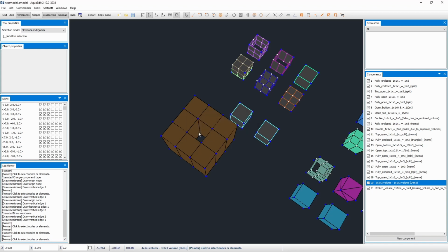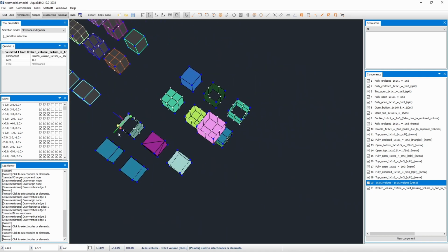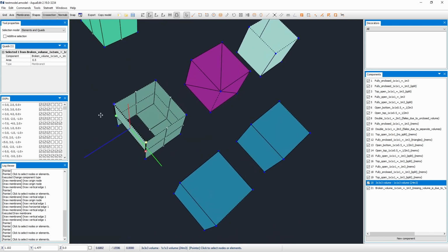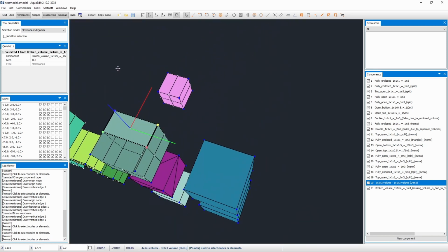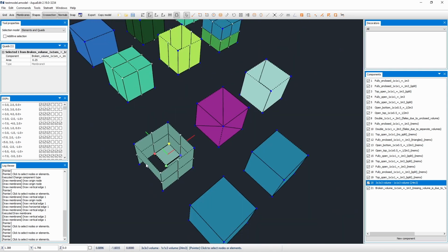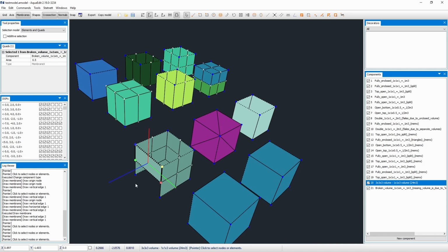Since we are looking at volume calculations, let us also see how the new algorithm deals with holes in the geometry. In older versions of AquaSim, the user had to manually enable volume calculations and tell AquaEdit if the top or the bottom was open. This allowed it to fill the holes so it could consider it as a closed volume.